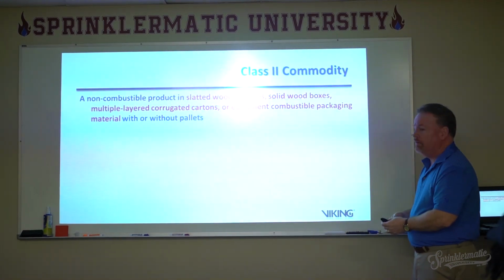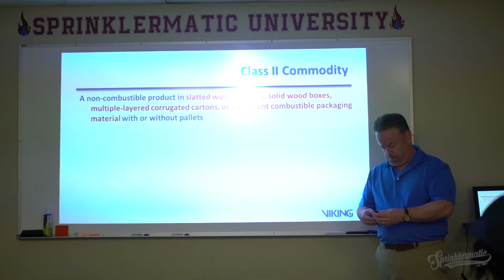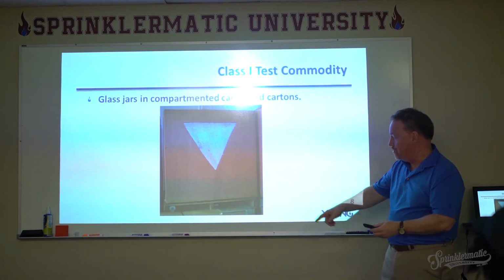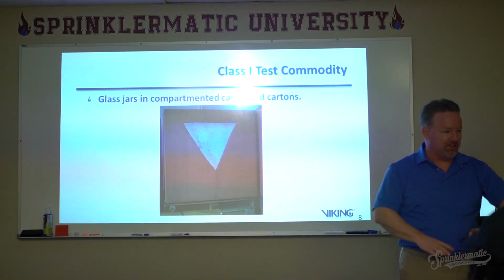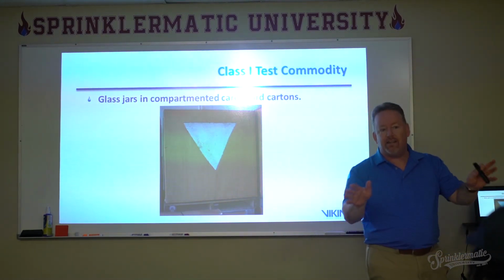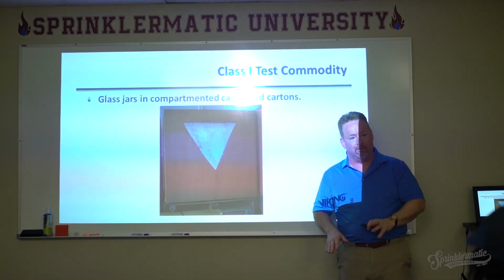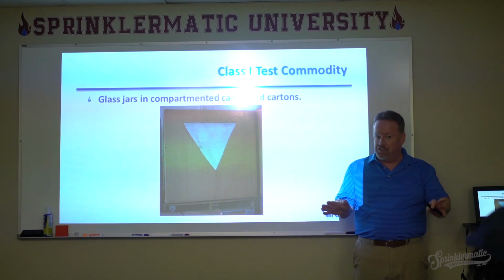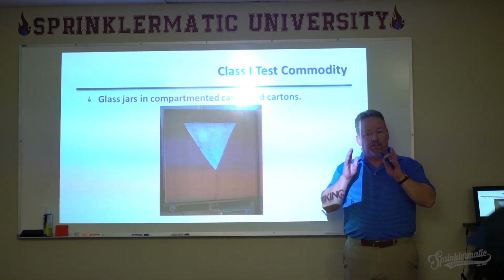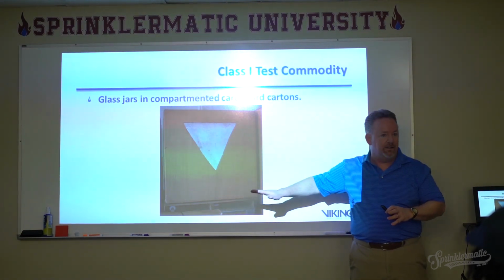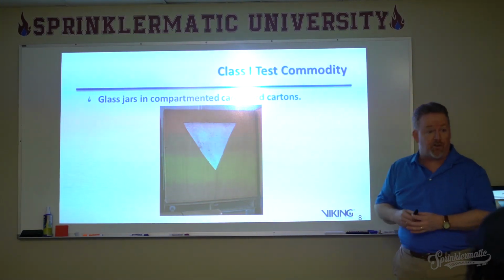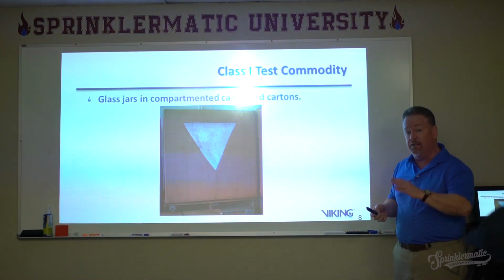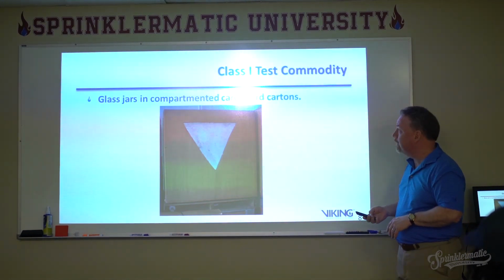The next, you said solid pallets. You're not talking about a solid deck, but just solid wood. We're just talking about a solid wood pallet, just the standard old-fashioned wood pallets. All right, no lightweight construction, no plastic construction in this one at all. The test commodities were tested on solid wood pallets. Now that becomes important as we get a little bit further on into the commodity classifications.